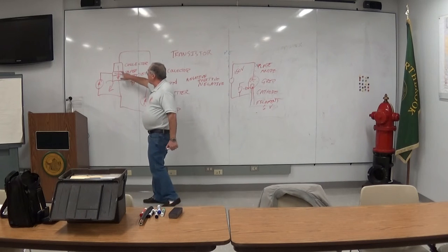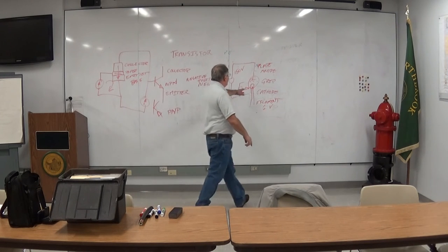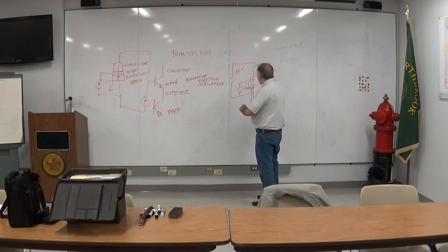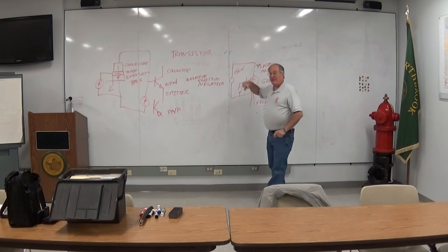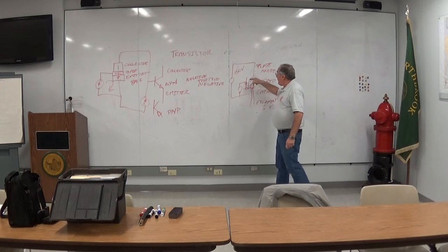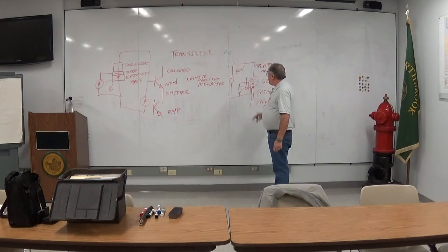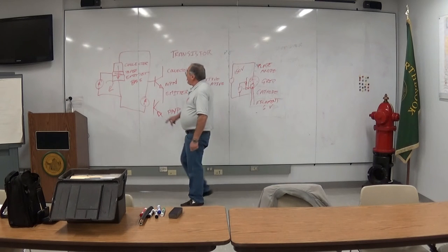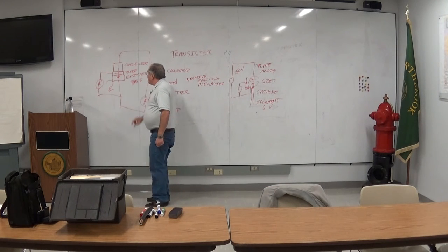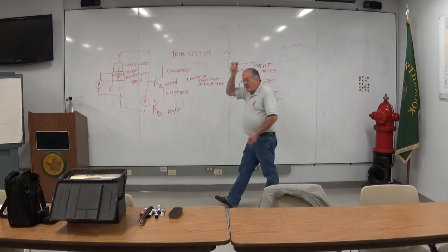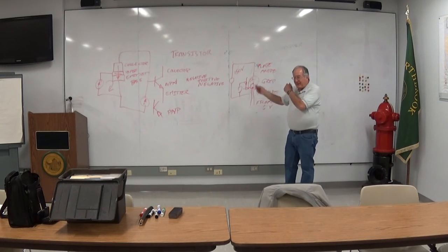This is a valve, just like the vacuum tube is a valve. Normally you're going to get current flowing here. I know the electrons go the other direction, but conventional current, plus or minus. The current is going to flow from the plate to the cathode, just like the current's going to flow from the collector to the emitter, even though the electrons are emitted by the emitter and they're collected by the collector.